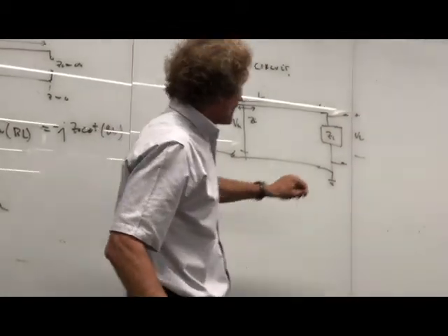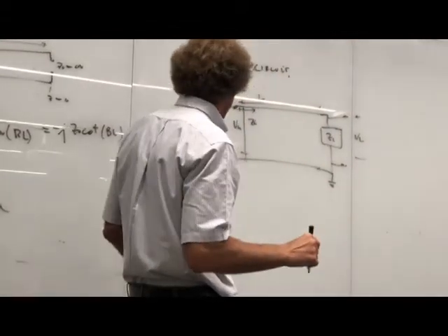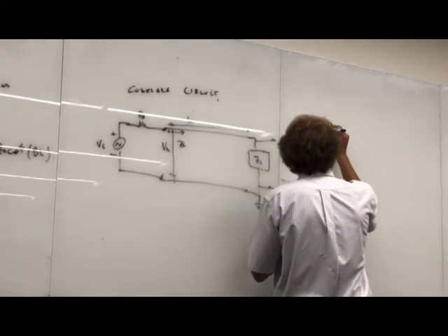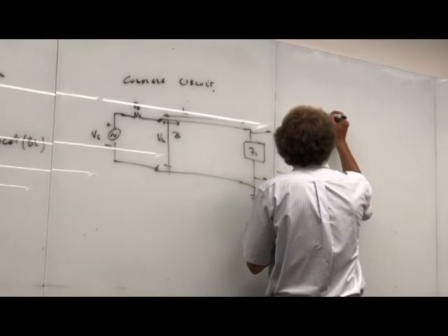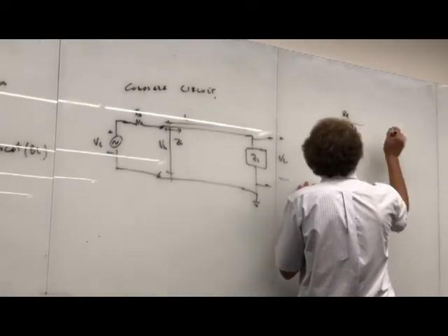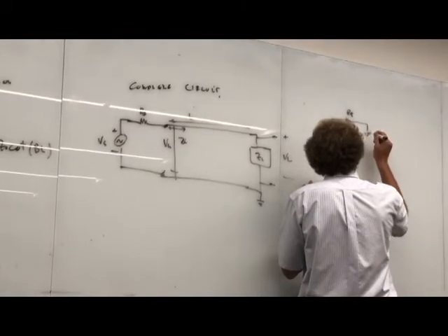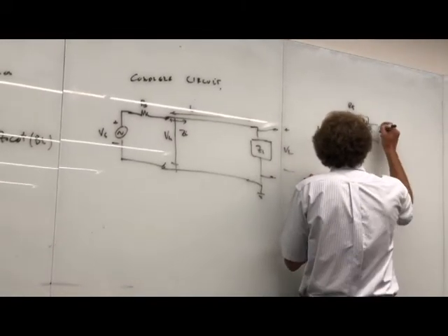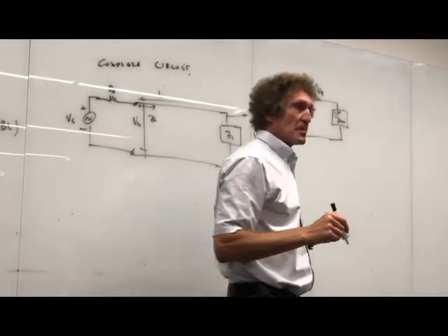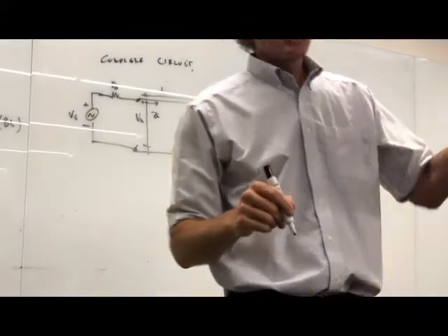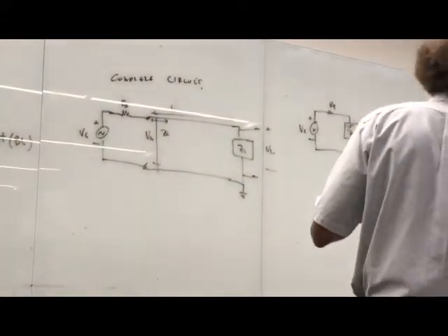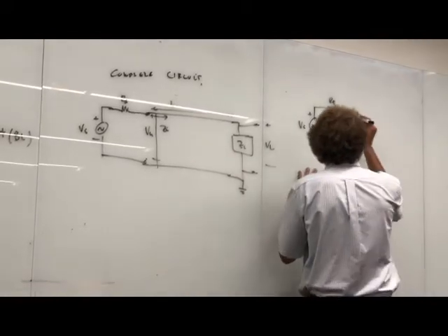Now, if I want to figure out the voltage here, here's how I have to do it. First, I do this circuit. I start with my VS, then I put R, the source resistance, and then I replace the transmission line with a simple impedance, just a box here, and I'll call that Zn. Are you with me? So the transmission line is represented only by a lumped impedance.